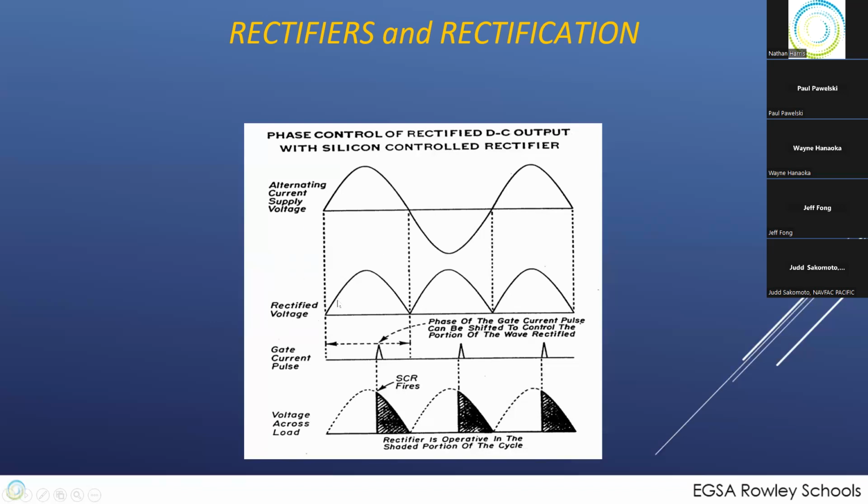And basically, then at the control side, you're hooked up, getting the same AC power, getting the same rectification. It's building up another capacitor, but instead of having a Zener diode time window drop, the gate current pulse that came from the Zener diode at the sensor triggering and letting go is what sends out the information to release that capacitor. What this ends up giving you is that you now have a way to do a timed load. You have a way to vary the amount of power coming into your control system based off of the same alternating current being used as a timer for both ends.